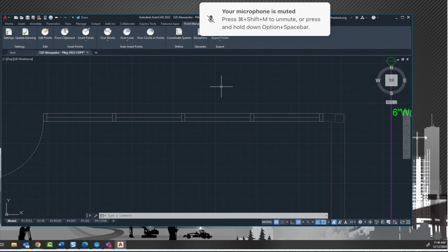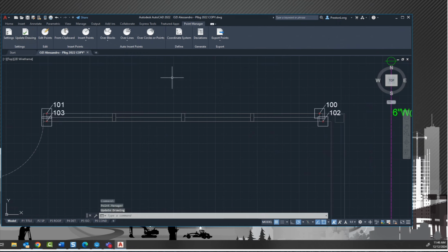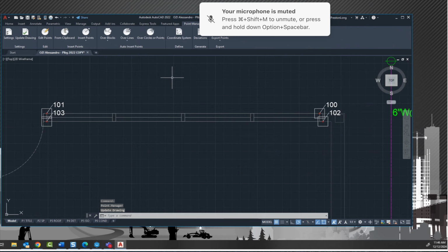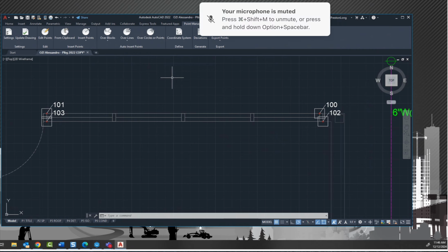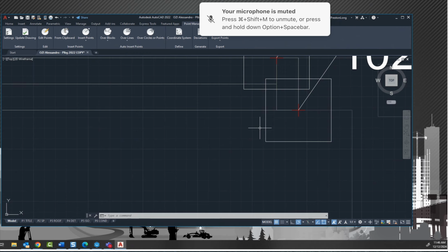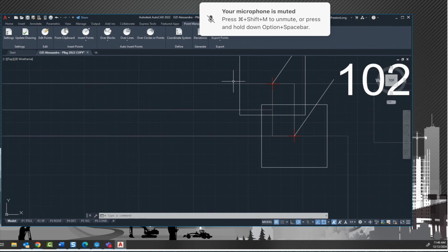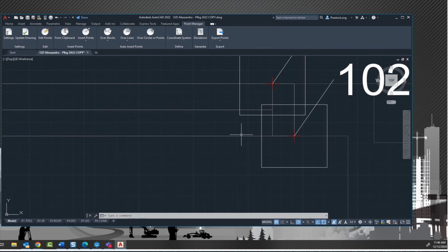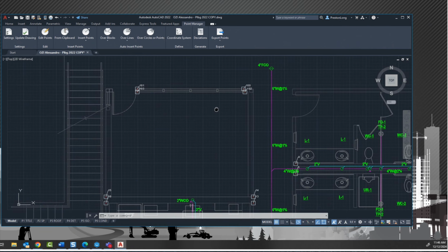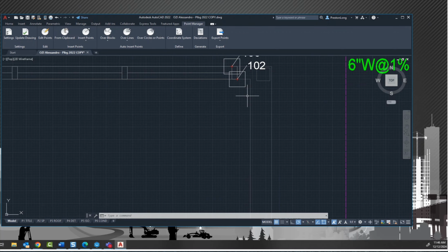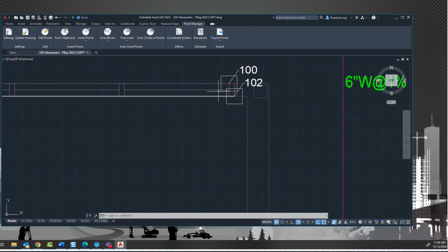And then every time you place a point or do anything, you need to go back and do update drawing before anything shows up. So if you think something got missed or something didn't work, hit the update drawing and then make sure nothing showed up. Right. I've had that happen already once. So I was like, oh, why is it not popping up? Yeah, it's like a regen all, but for point manager. I don't know why they did it that way. It's just one of the things.